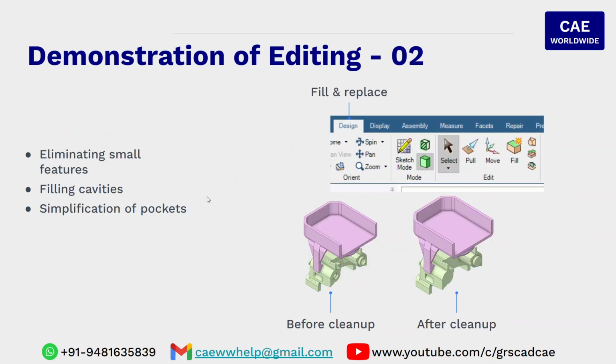The next example is about snapping geometries. There are two bodies which need to be snapped. Let's say the problem says that we are interested in identifying what is the push force required for assembling these two bodies. Assembling in the sense that, because of the push force, the snap is going to expand, slide through the flat wall and fit into the cavity.